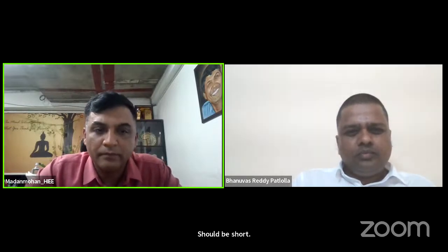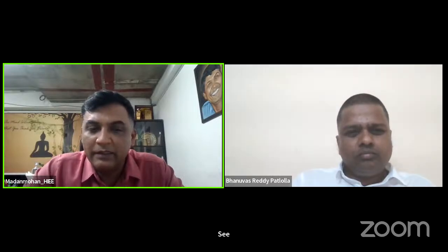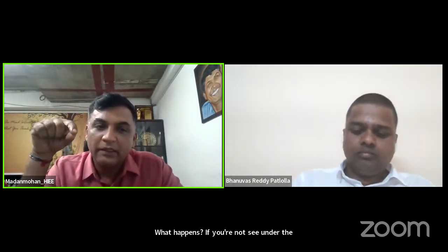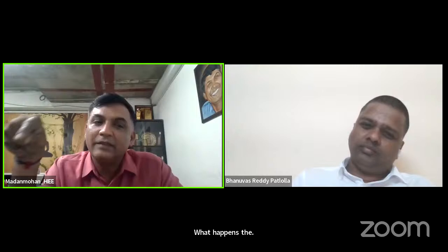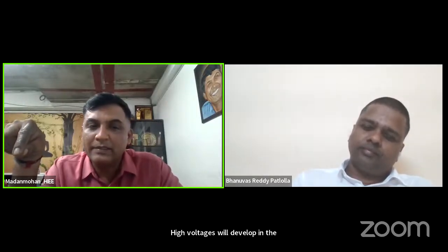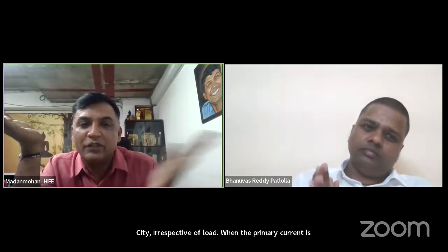Yes. Why, sir? See, actually, the driving function of the CT is the primary winding. Under loaded condition, if the CT secondary terminals are open, what happens? High voltages will develop in the secondary winding, because irrespective of connected load, when the primary current is flowing in the primary winding, the same ratio of current will be given in the secondary winding.